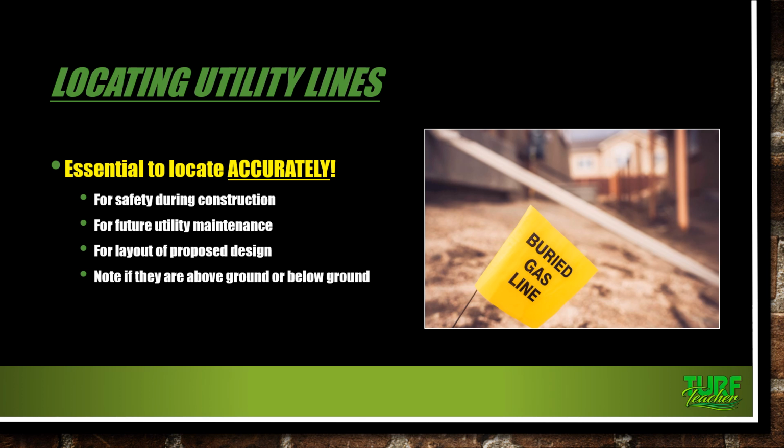But guys, mark these on your site plan. Call 811 when they come out and do it. Measure where they are at and give yourself some sense. Try to get it as accurately as possible where the power is, where a phone and cable is, where water is. And this will be good information for the client to have as well. So put it on the base plan.